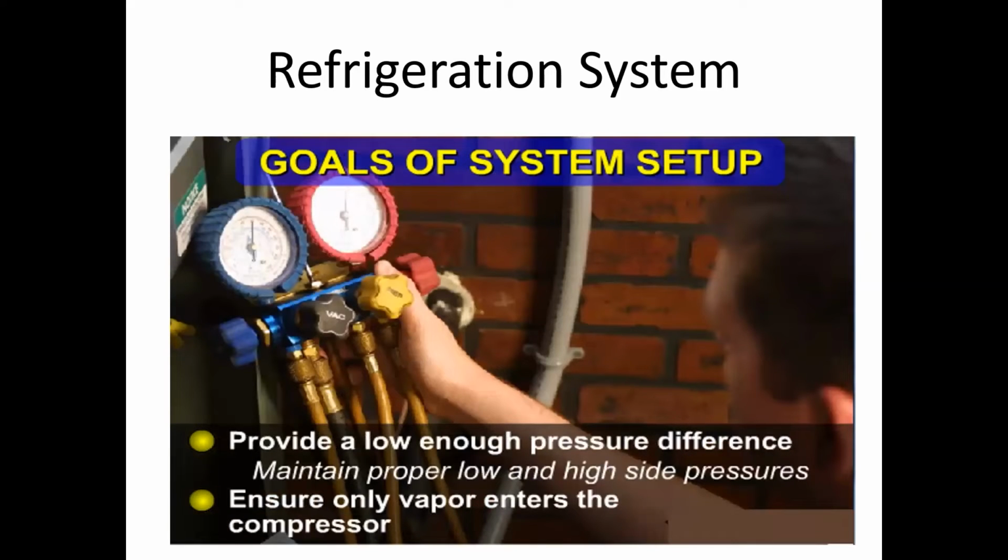If you're not doing that, you're going to have compressors fail, especially with 410, because 410 is what's considered to be hygroscopic, meaning that it sort of absorbs moisture. And as we move into 2025 with new refrigerants, we will see that with these new refrigerants as well. You've got to pull it down.